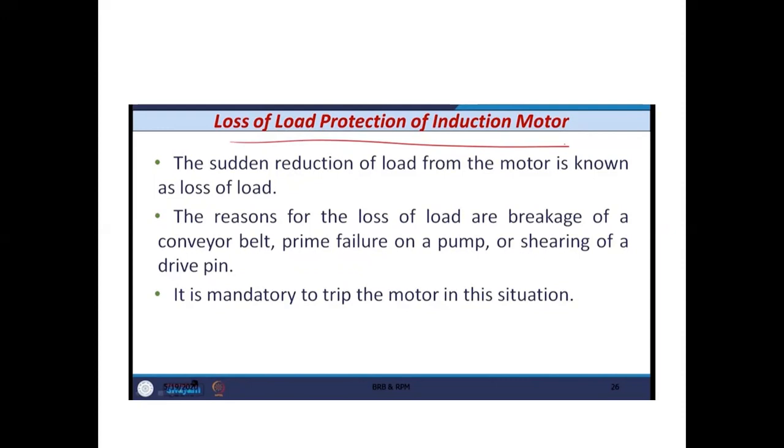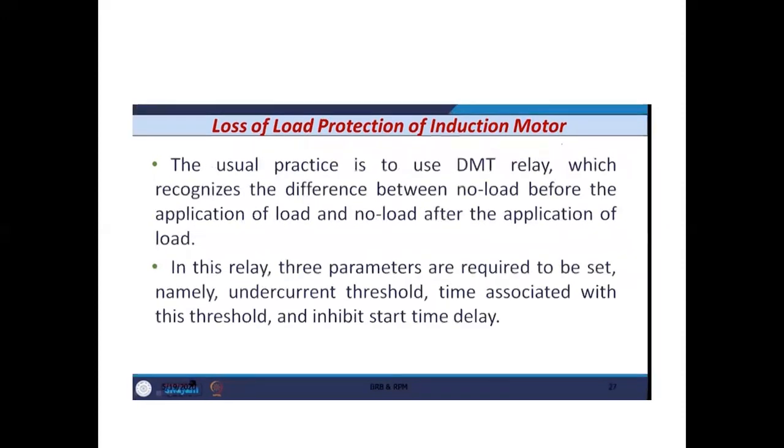So it is mandatory to trip the motor in this situation. When the load is suddenly taken away from the motor, the usual practice is to use a definite minimum time delay relay, which recognizes the difference between the no load before the application of the load and the no load after the application of the load.